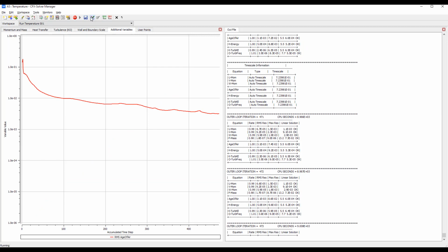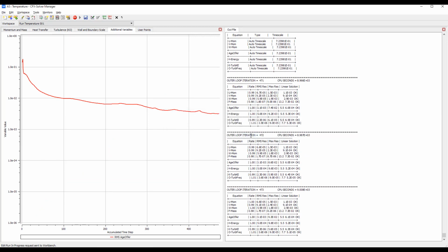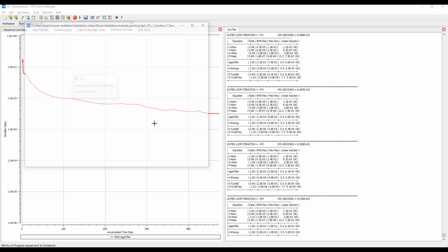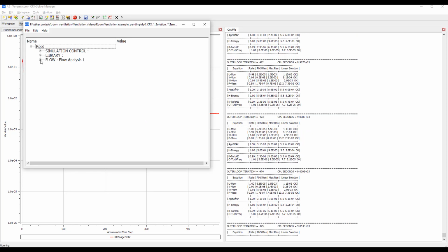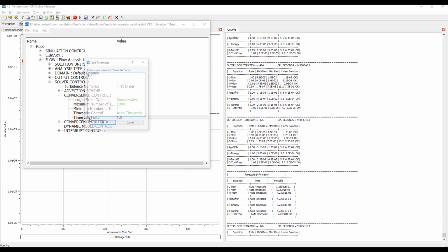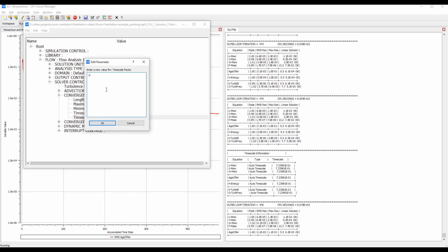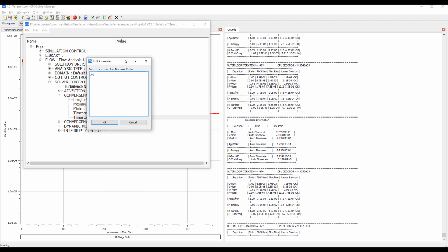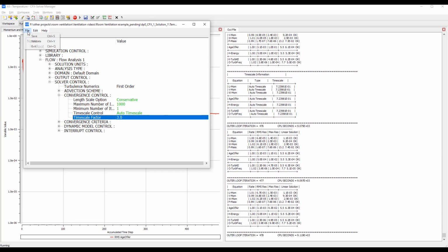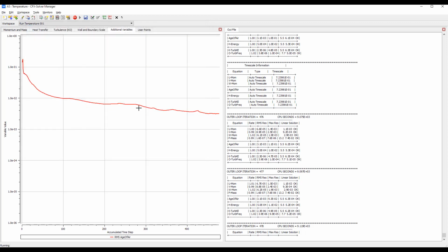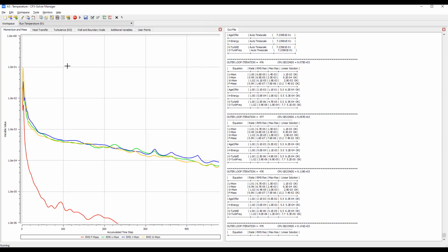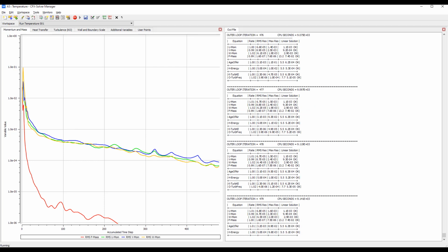we want to speed this up a little bit. In CFX, there's a nice tool that allows us to quickly change the settings. So we're going to speed up my simulation significantly since the flow has pretty much converged. So I'm going to change this time scale factor to 3, which allows us to increase the speed of convergence by 3, and we should see convergence speed up appropriately.